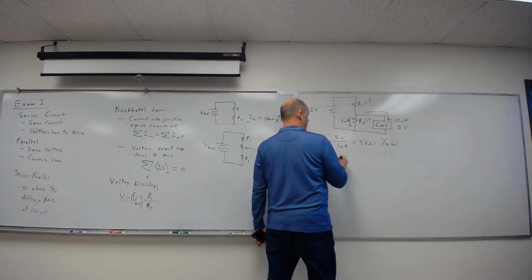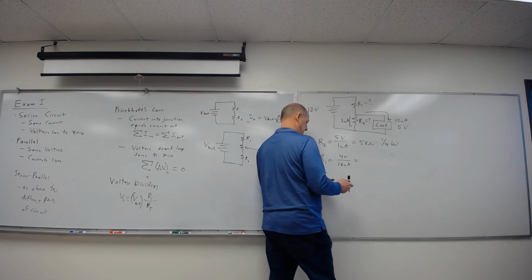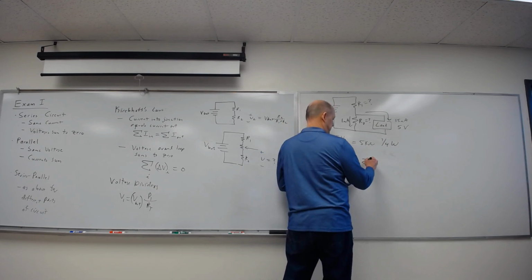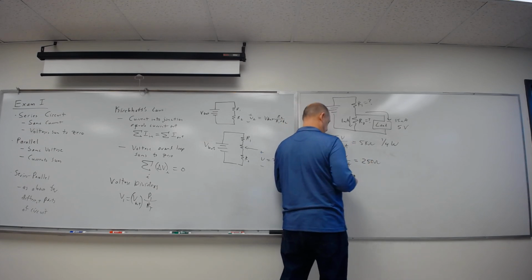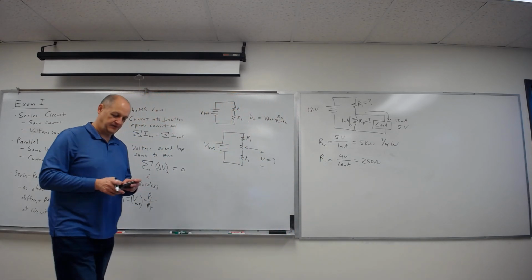Now R1. It's going to be 4 volts over 16 milliamps. So I have 4. That's 250 ohms, right? Yeah.